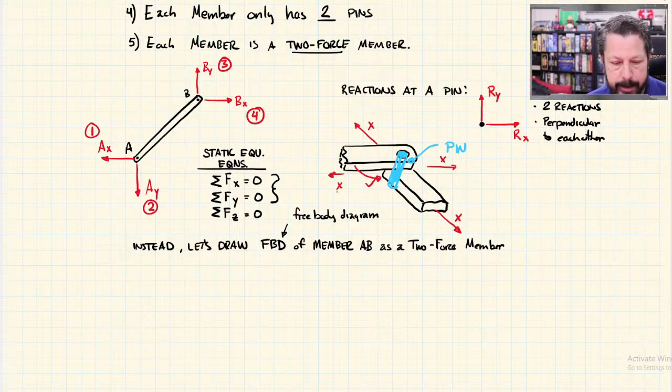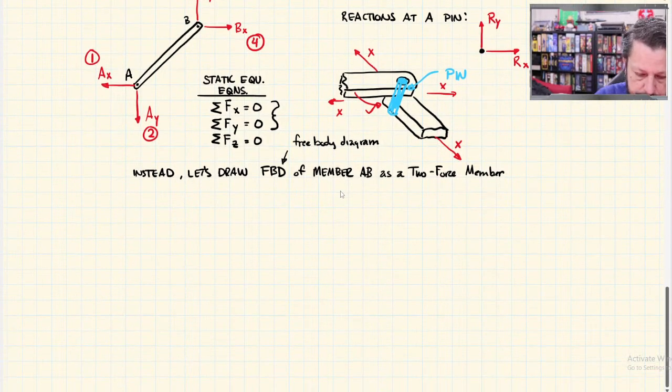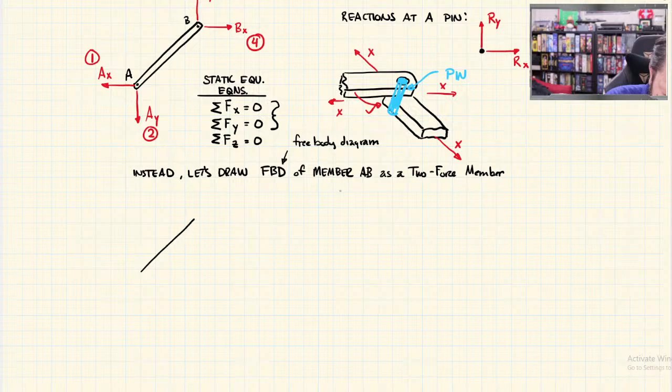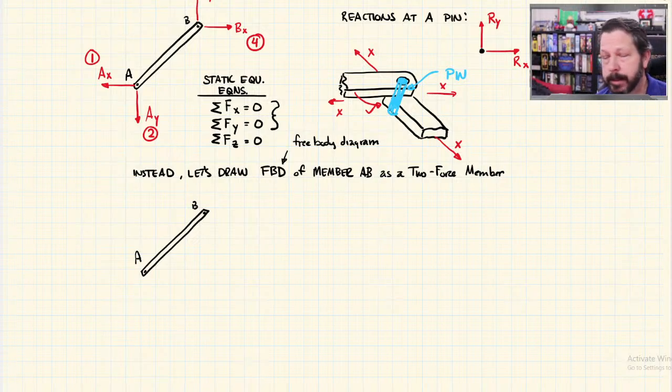Okay, so what that lets me do is I still draw AB. But when I follow all the truss assumptions that we stated earlier, then I can say that if this is a two-force member, I followed all the rules, and I'm going to analyze my truss, even though it may not match the real world exactly, with the external forces only at joints and all that.